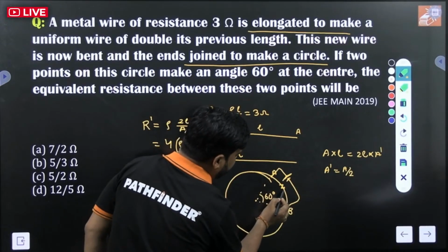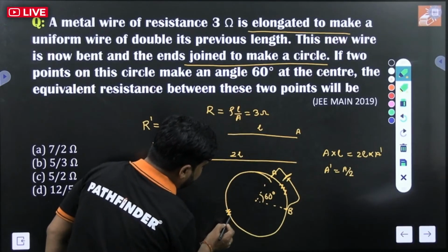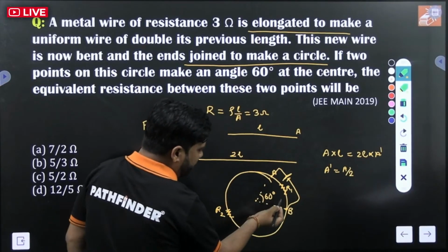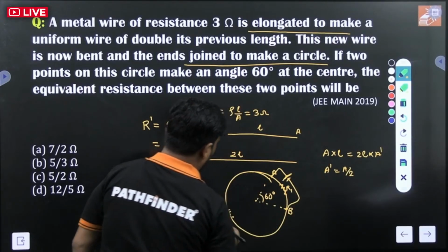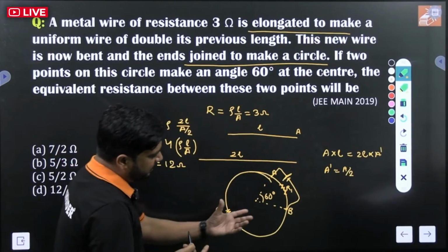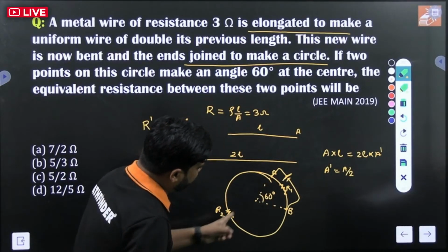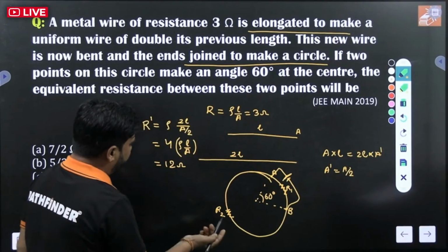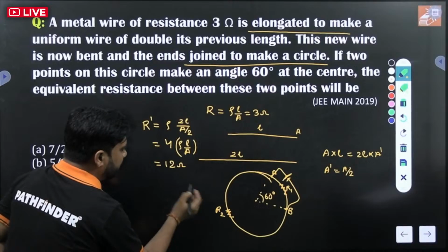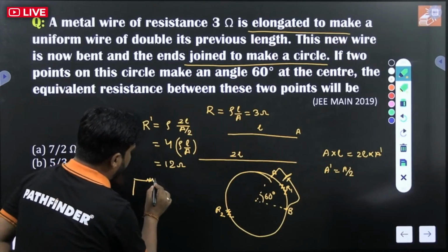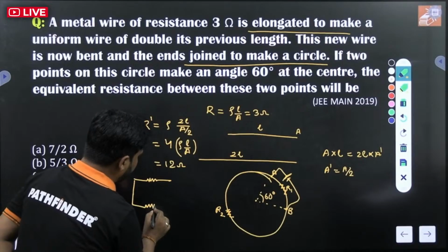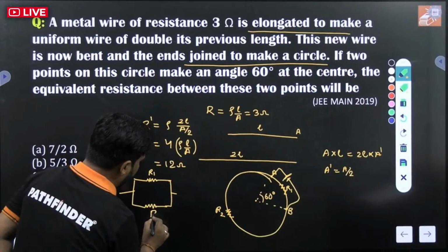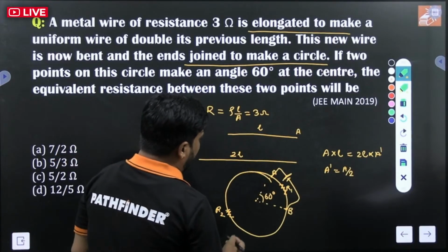If this is one resistance, for example, and this is another resistance, its value is, for example, R1 and its value is R2. So don't you see that these two are connected in parallel? You can see it, and you can just try to visualize. Don't you think that R1 and R2 are connected in parallel? It's having same potential difference, VA minus VB. So here, these two are connected in parallel. So we can reduce the circuit like this. This is your R1 and this is your R2.